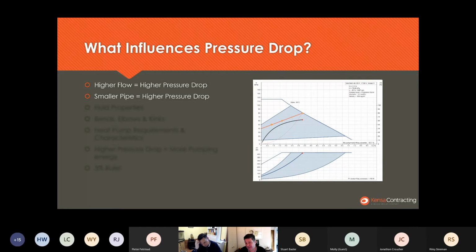So 80 kPa up to maybe 120 kPa will be typical for the pressure power that a pump can exert internal to a heat pump. And I'll come back to why that's relevant in a minute. But when we're talking about bigger plant room projects where you've maybe got a central set of pumps that are driving multiple heat pumps, then being up 200, 300 kPa is not unreasonable in those environments where you've got a specific pump to select.